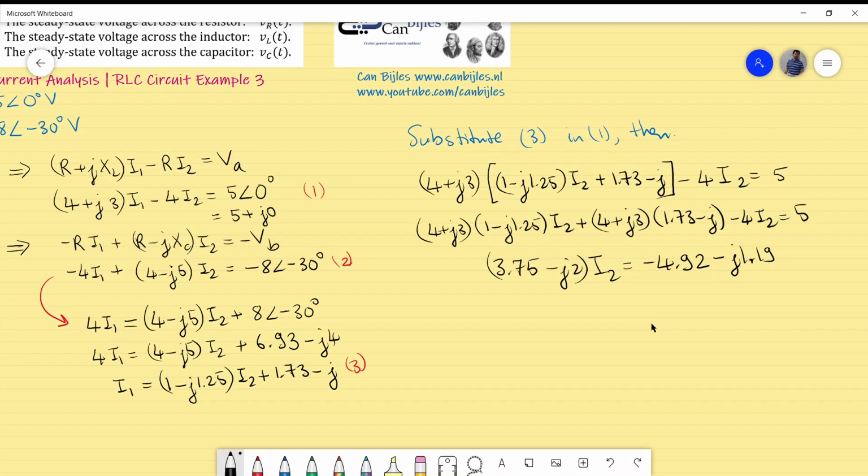Now, for calculation of I2, it will be helpful to represent this also in polar form, and also this one, so the division will be much easier. If I now convert this and this to polar representation, it will be 4.25 phase minus 28 degrees times I2, which will be equal to 5.06, and the phase will be minus 166 degrees.